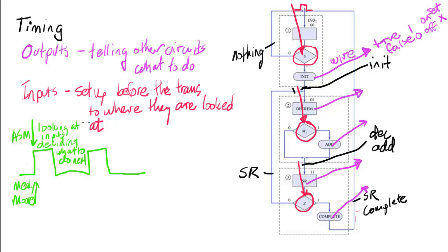And it's got to get all that stuff done before this next clock pulse. The Mealy and the Moore circuits are doing stuff like shifting right, adding, decrementing, initializing. And they're setting up inputs that trigger the algorithmic state. And that's all got to be done by this clock cycle. And then we just get a repeat here, and it keeps going forever and ever.